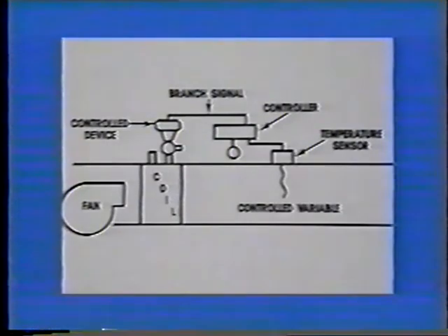Now that we have covered the source of clean, dry, and oil-free air and are able to choose the final control devices required, we will now discuss the function of the pneumatic controllers that are required to make the system function properly. The controller is a device that senses a condition and takes an action based on a change in that condition. This sensed condition may be temperature, pressure, or humidity. The controller provides an output signal based on that sensed condition.